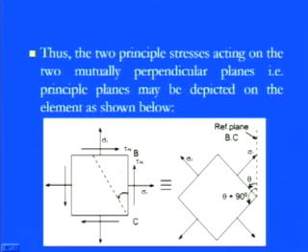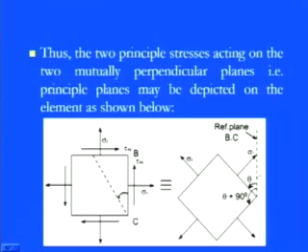So we have the pretty simple element which has all those three types of stresses: sigma x in this direction, sigma y in this direction, tau xy in this direction. It is equivalent to this direction. You see this is my reference plane, that is the BC plane. If you rotate this by the theta as we calculated in the first case, you have sigma 1.